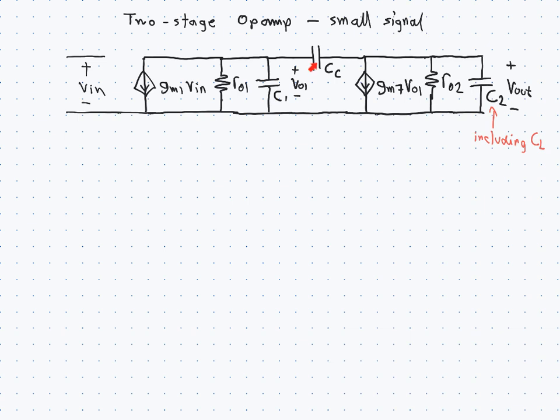And that capacitance is normally a lot larger than that, which means that we can ignore the parasitic capacitance here. And that means that the dominant pole is going to be the Miller capacitance times the output resistance of the first stage, or 1 divided by that, like so, as we have seen before.